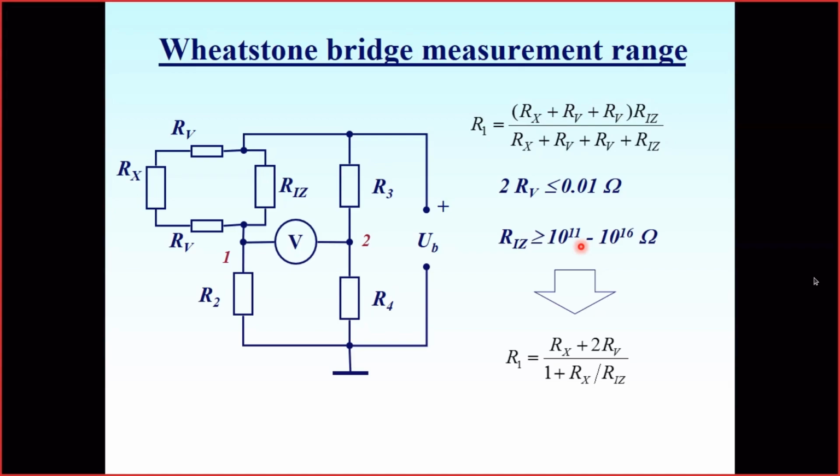So it's very big. If we speak about the corresponding currents, for such a measurement the voltage is of the order of volts, and we have a resistance of the order of 10 to the power of 12. So we speak about currents of 10 to the power of minus 12, picoampere currents, and even probably smaller.